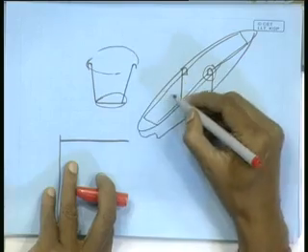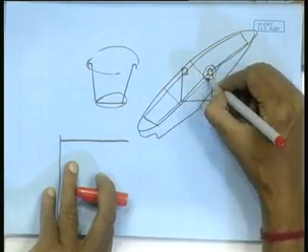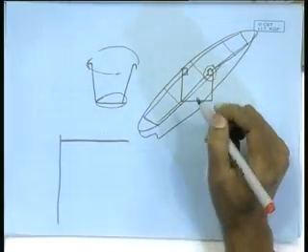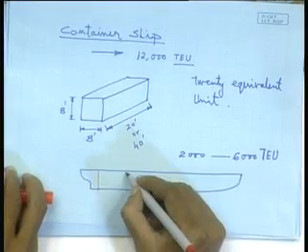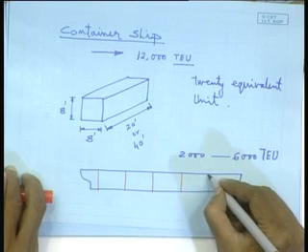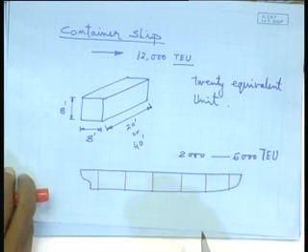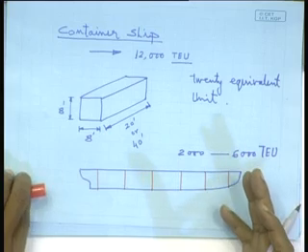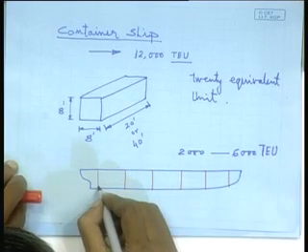Transverses are needed, because while you have the bulkheads, whatever that concept of bulkhead, that remains, because one thing you can see, these transverse subdivision bulkheads, they are a must, whatever be the ship type. Why must?